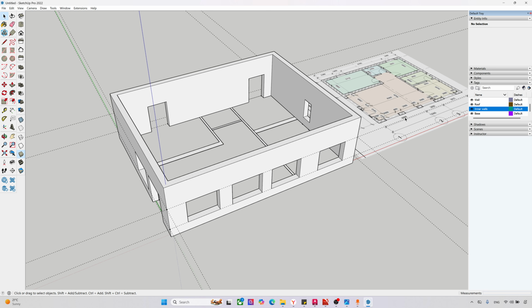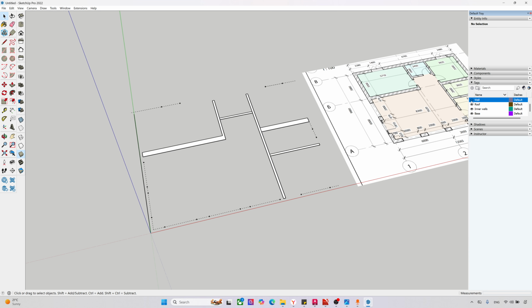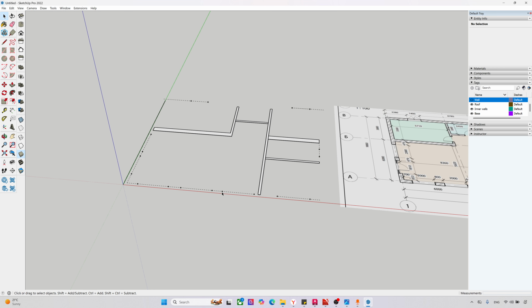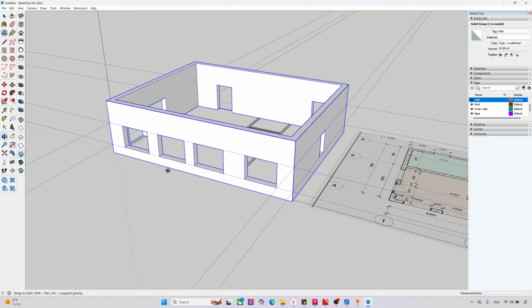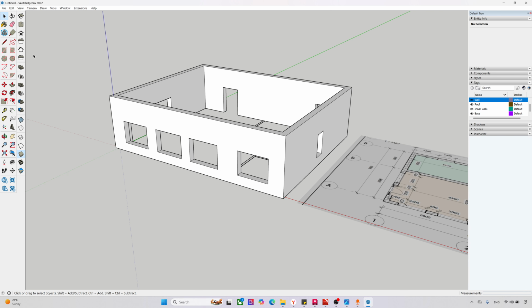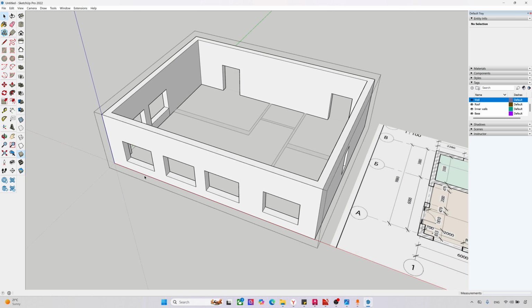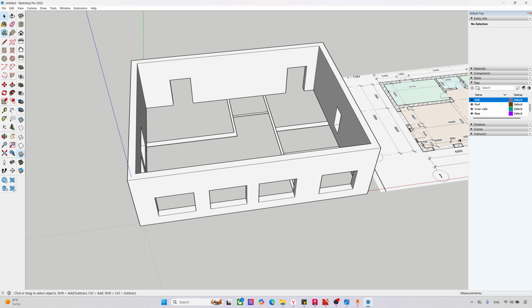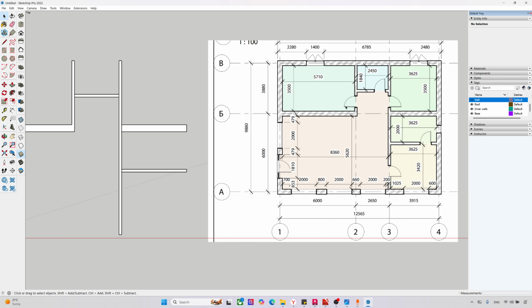We have it. And now let's close it, escape, and then hide inner walls. Now I don't need the exterior part, I need only the inners, but one more thing, I don't need these construction lines anymore, right? I'm just opening this again and Edit, Delete Guides. I don't need it. Done. Okay, hide it again. What I'm going to do is create the space for doors.